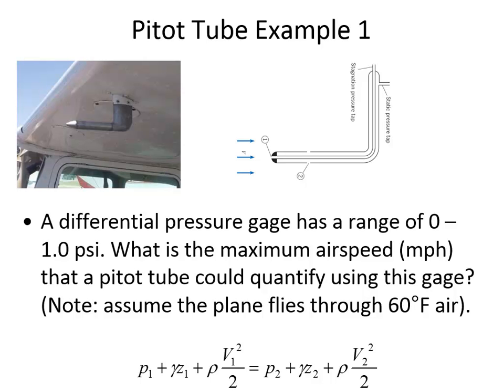Remember that the definition of a pound force is a slug accelerated at one foot per second squared. So the units do work out on this. If you substitute in pounds force for slug times foot per second squared, then all the feet units will cancel out except for one in the numerator, then we'll have seconds squared in the denominator. We'll take the square root of that, so the units do work out. 348.6 feet per second.